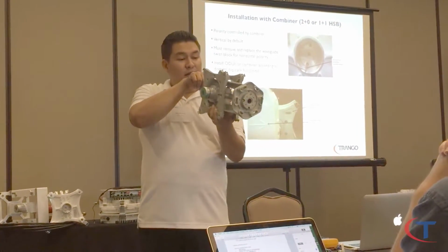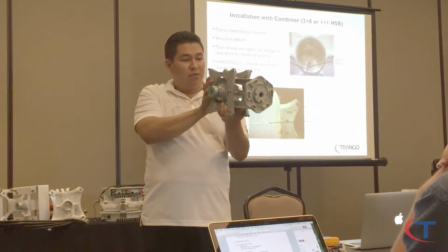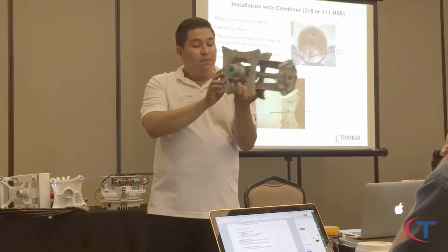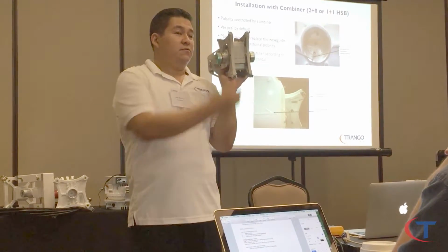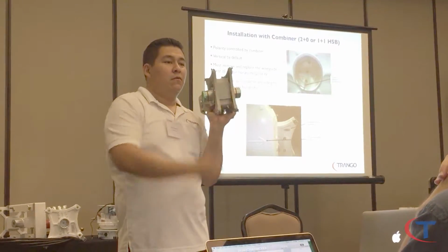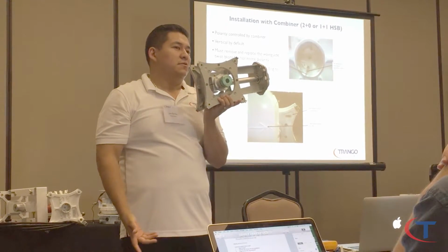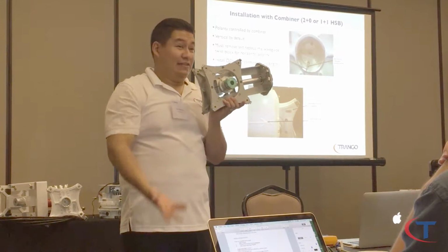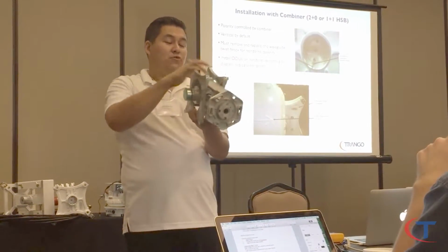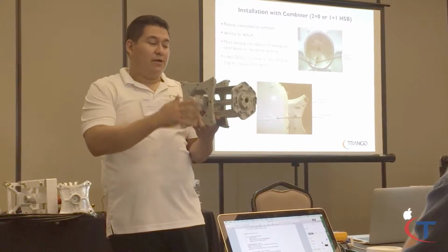Other thing, again, on top, the actual bubble level. Make sure that bubble is centered, because it can be entirely cross-polarized. You don't even know it. Now, on the back of the combiner, there's markings that say which side is vertical, which is horizontal, right here. If you install it like this, it's going to be backwards. So make sure you install the other side the same, backwards. But again, logic says, okay, my bubble should go up, and it's pointing up. So I'm going to pass this around.